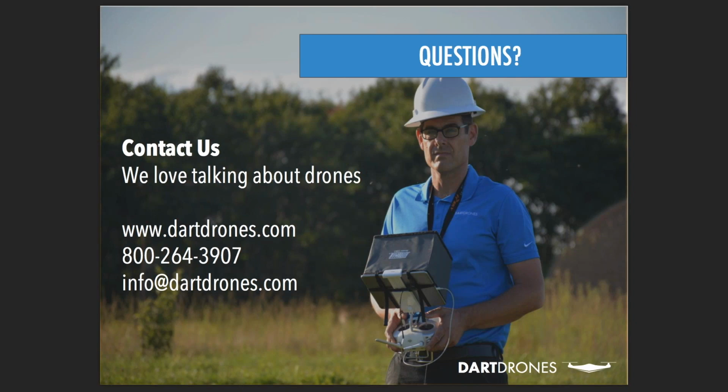You can pick that drone up, go closer to the next section that you're going to be mapping, open up that same mission. DroneDeploy remembers exactly where you took off, and you can just continue that mission from that new location where you're going to be closer to where the drone's flying now, so you can keep line of sight. You can rinse and repeat that to map any size area that you could potentially want. We've had maps made of, I believe the biggest was recently 10 square miles. So there's not many limitations there.